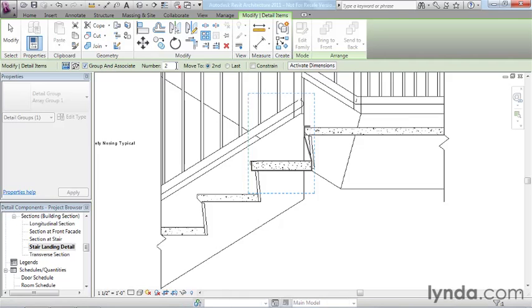So it looks like I've got 3 treads showing here. So I'll go ahead and put in a quantity of 3. And we have 2 options for how to set the distance. If you choose second, you're setting the space between each item. If you choose last, you're setting the overall space of the total array, and it will just fill them in between.